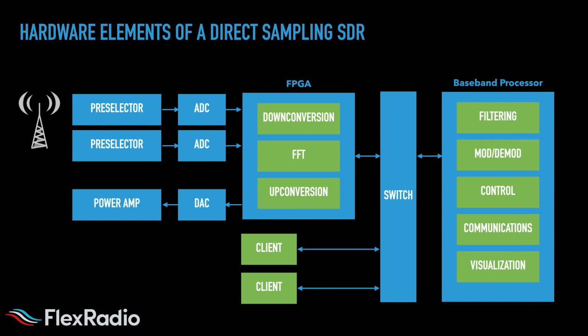It's not often that hams are in this situation, but some common situations that occur are if you're near a broadcast station, if you're a multi-op contester where there's multiple radios in the same location, or if you're at field day. Any of those things are likely reasons to have a preselector, and they do need to be actually created in hardware filters made from inductors and capacitors and those kind of components.